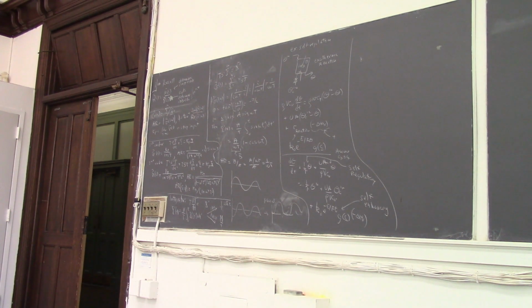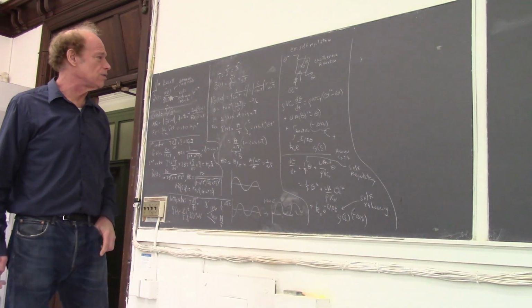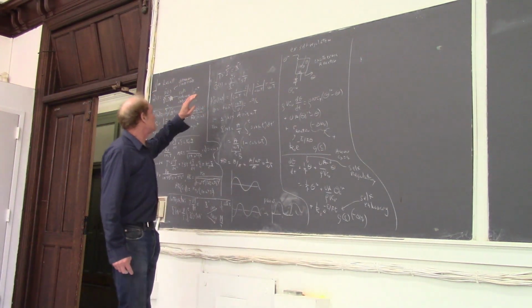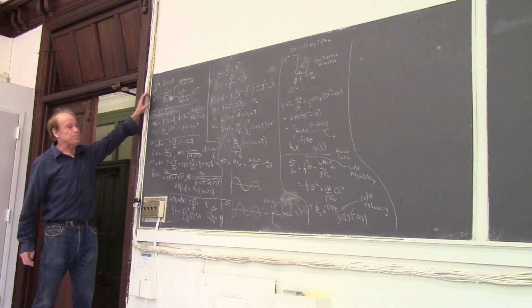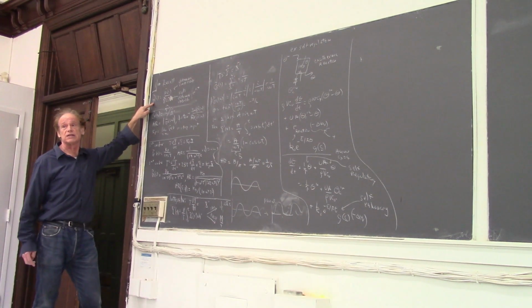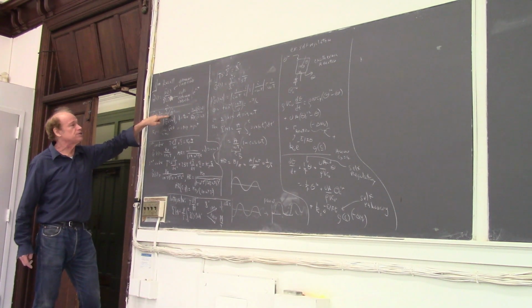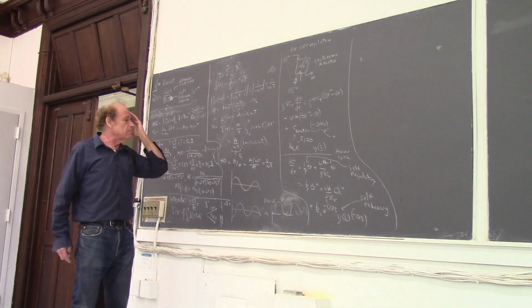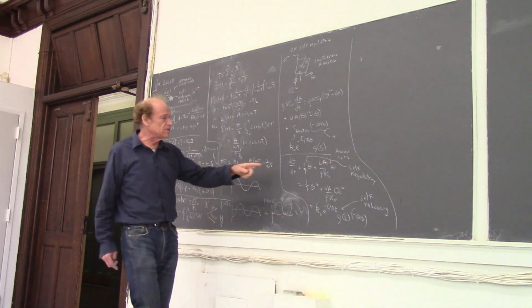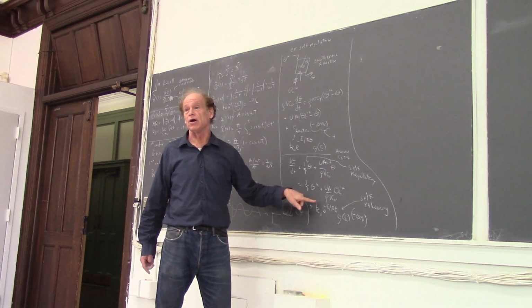So this G function, is this a part of the rate of reaction, and is that a function of theta? Okay, so G is the transfer function. F typically is y prime. So y prime is G times x prime tilde. Typically when I'm doing this, I'm trying to solve for the output, y prime tilde. So G, remember, is y prime tilde over x prime tilde. In this case y is theta, and x might be theta in or theta c in, either one of those.